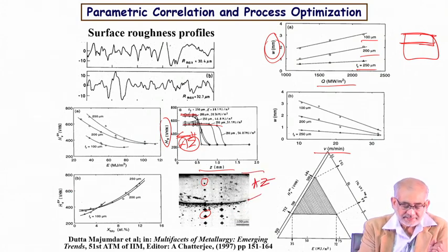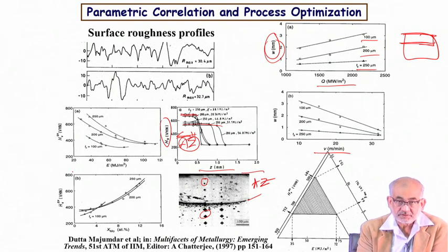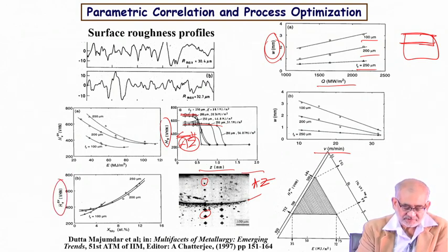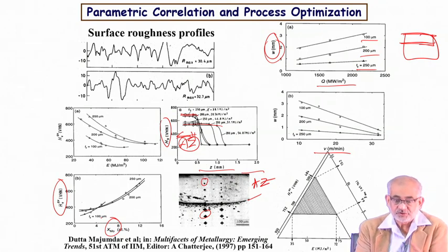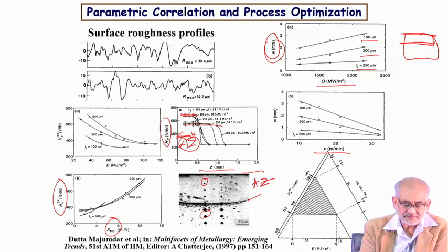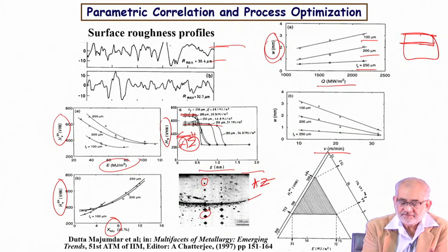Now we also carry out certain characterization in terms of the variation of hardness as a function of molybdenum in the solid solution, dissolved state. Also we try to characterize the variation of hardness as a function of energy density. We measured the surface roughness, and typically the amplitude variation is fairly small, and the average roughness is 30 micrometer for one set of parameters, can be 32 for another set of parameters.